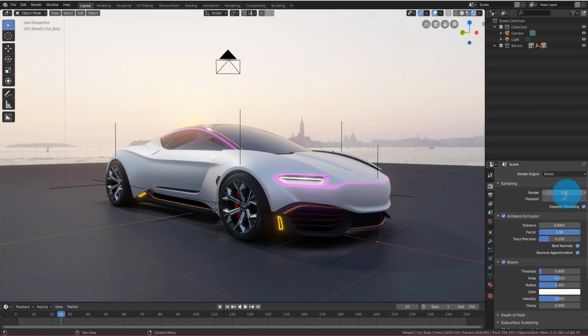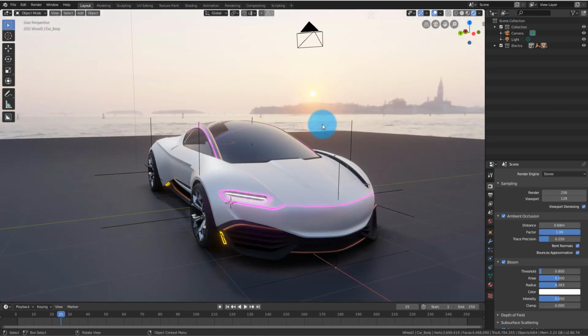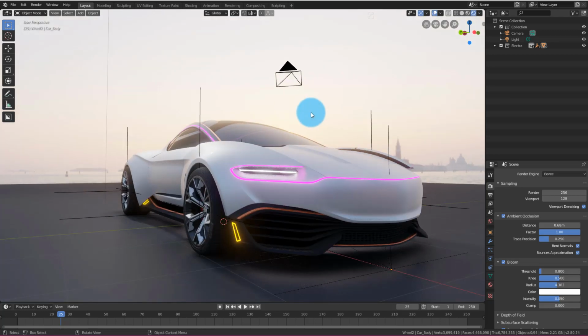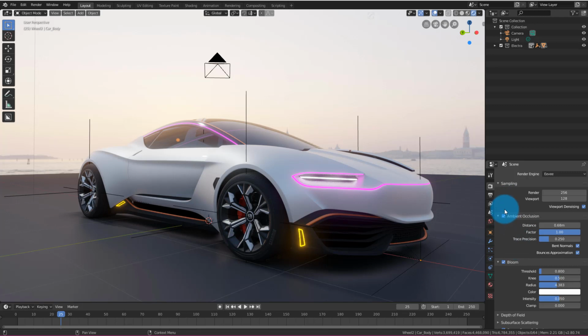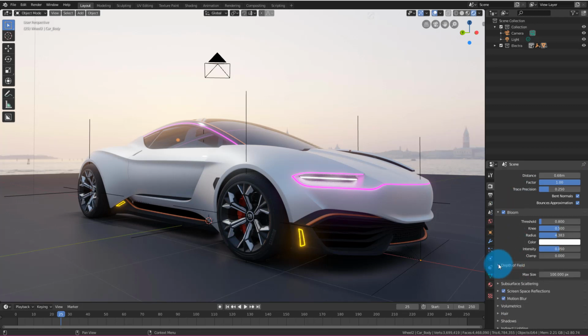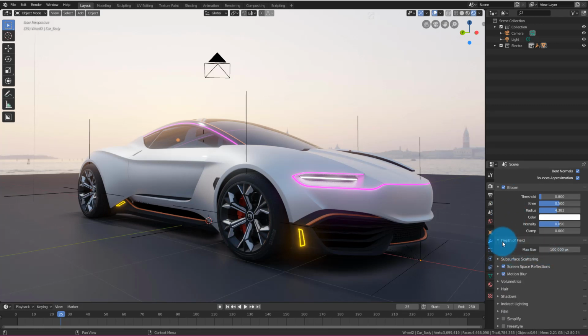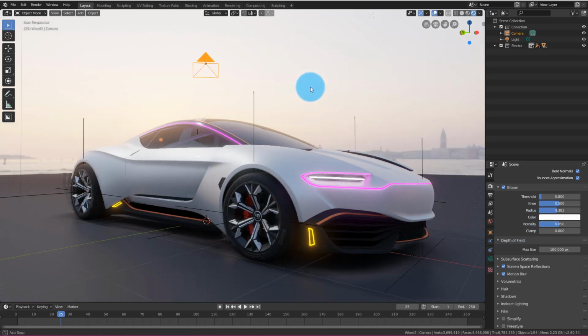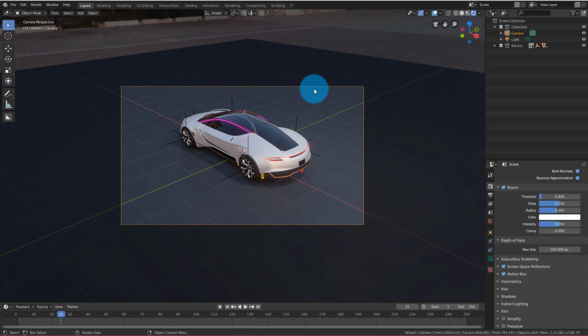And here in the render settings, I changed it to 256, and the render you saw in the end was 256. But then I also do a 16 sample, and basically at 256, every frame is gonna take about 40 seconds, and then at 16, every frame takes about 25 seconds. So it all depends on what type of quality you need and what kind of time you have.